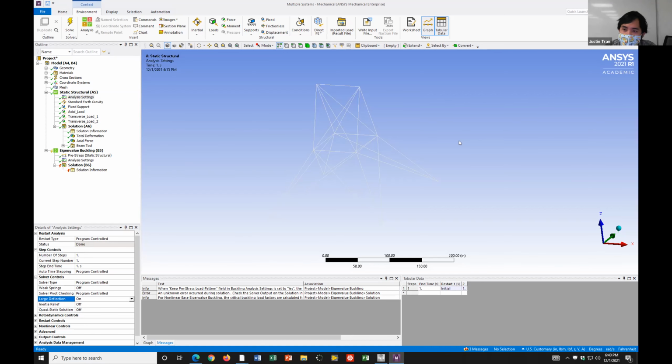The reason for that is because the housing is in a very central location on the part, and a lot of the other parts attach to that housing. Any change you make to the housing is also going to change the vibrating properties of everything beyond that too, right? Whenever you change something central, it affects everything it attaches to.